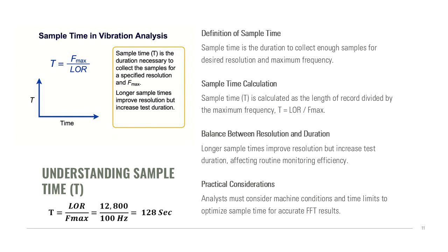Analysts must consider machine operating conditions and time constraints when setting sample time. Collecting sufficient data ensures accurate FFT results and reliable fault detection, but excessive sample times can lead to inefficiencies in data collection routes. Relationships between parameters.